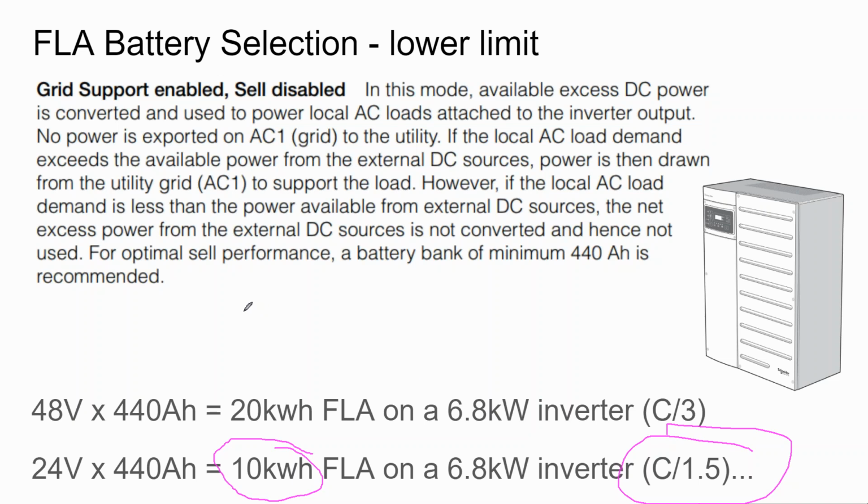Most homes use around 30 kilowatt hours a day or more. So a 10 kilowatt hour battery bank is only going to be maybe 25% of your daily energy use. Having a small battery doesn't give you whole house backup power. Instead, they relegate it to minimum loads.